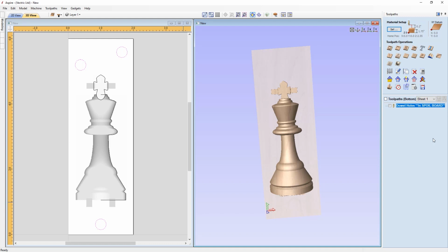We're going to take our material block, we're going to turn it over, and we're going to push our material block down on top of those dowels, and that way it will securely be put into place and it will line up correctly. Now again, you're going to have to affix this down to your machine either by using your clamp, screws, or double-sided tape, or whatever your method is.